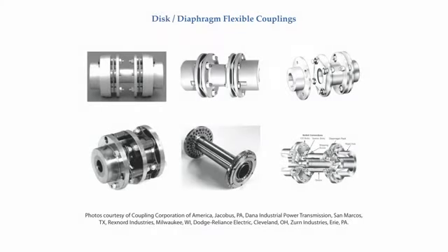And yet here is another design family of flexible couplings. These couplings also do not require any lubrication. These are disc or diaphragm type couplings. A metal disc or contour diaphragm elastically bends to accommodate slight misalignment conditions. There isn't any sliding of one part against another, so no heat from sliding friction is generated.